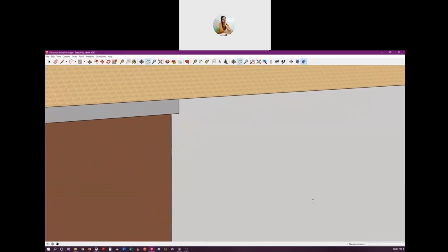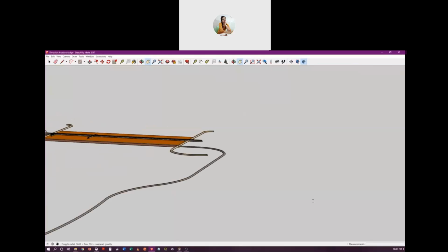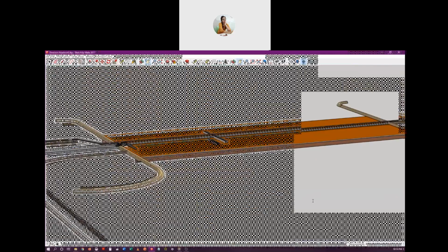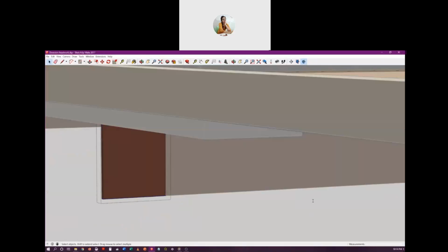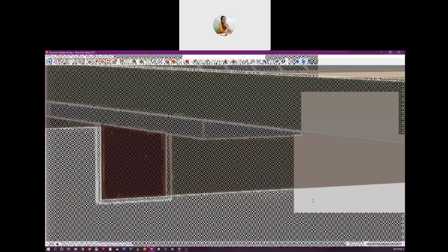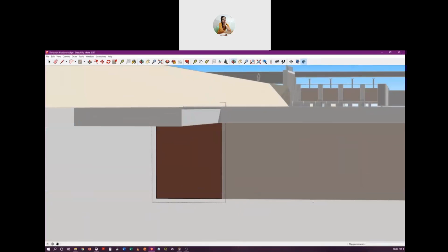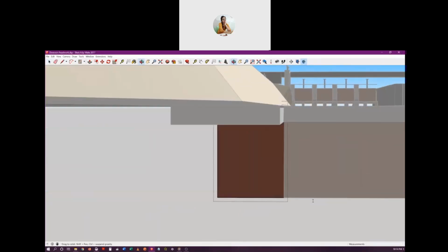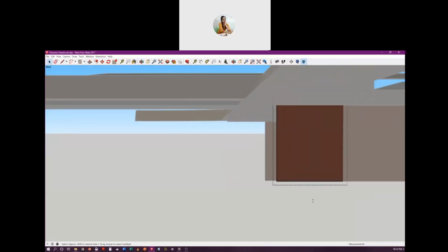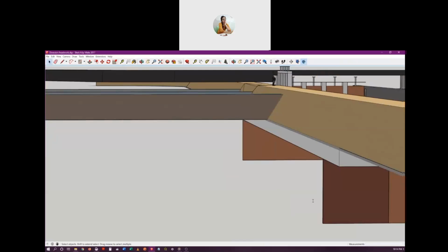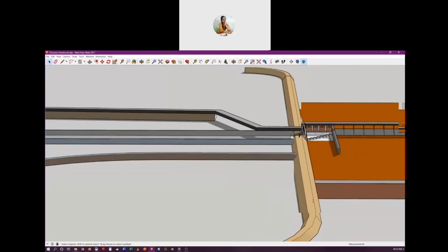That can be prevented by extending these cutoffs to a considerable length and inserting them into these embankments, so that when water tries to take this sideway, it also has to go through a longer path, because there will be cutoff in the horizontal direction also, and therefore the leakage will be reduced.